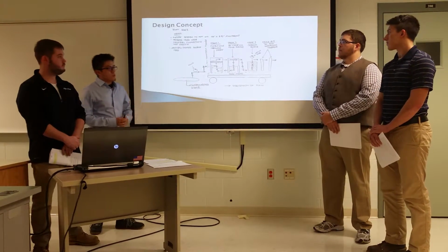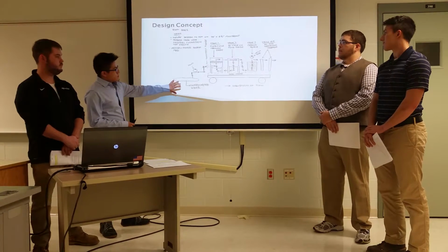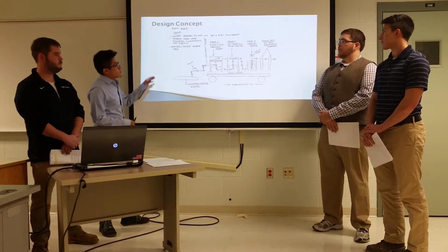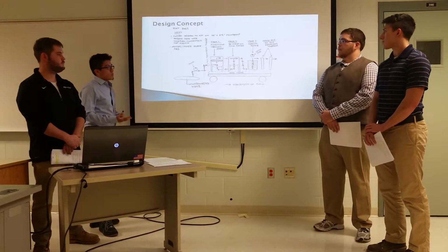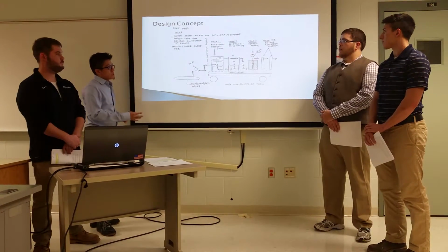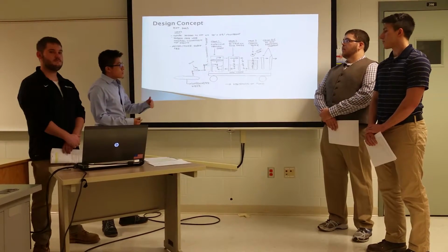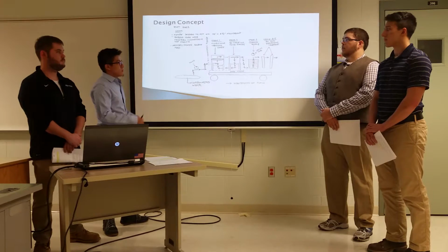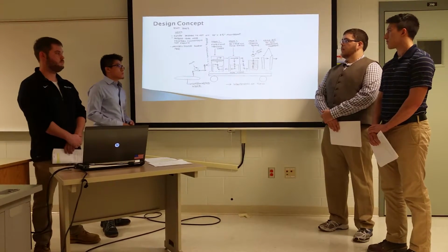Here we have all 5 stages laid out in a plan. As you can see, first is the contaminated water, which will be pumped through to the first stage, where a grate, as I said before, will separate the contaminants. The second stage is essentially just a second filtering tank, which is going to recycle all of the fluid back to 2 ports, the waste and the first filtering system.